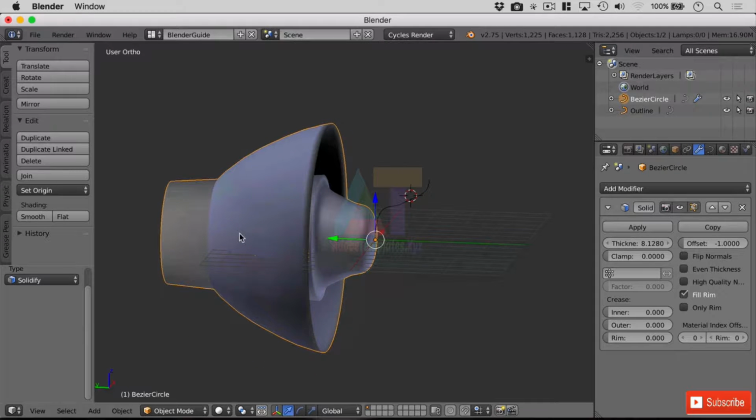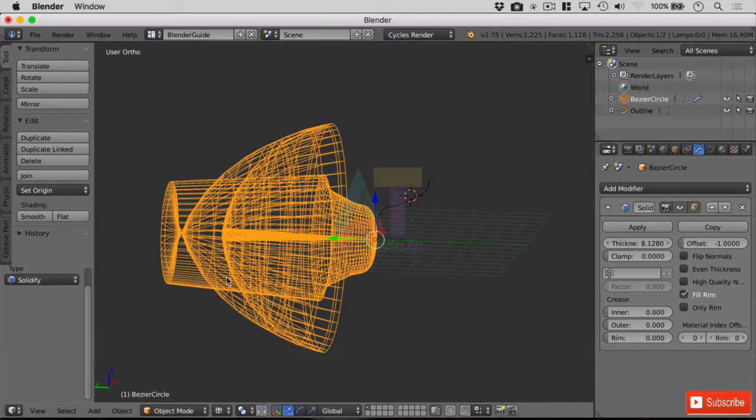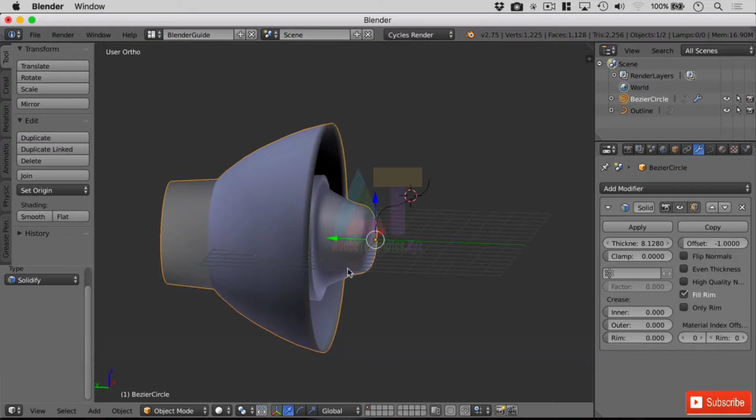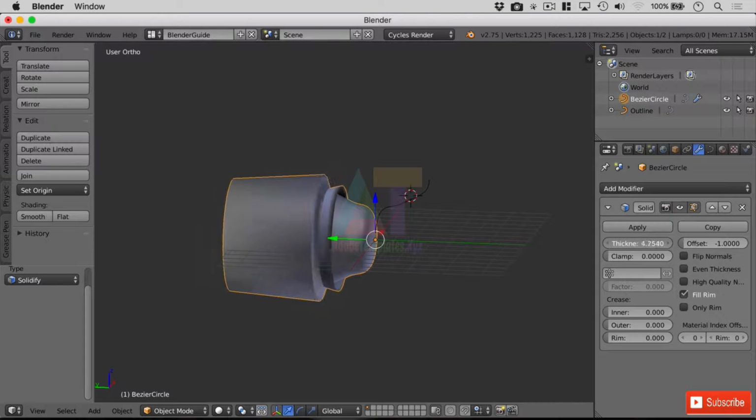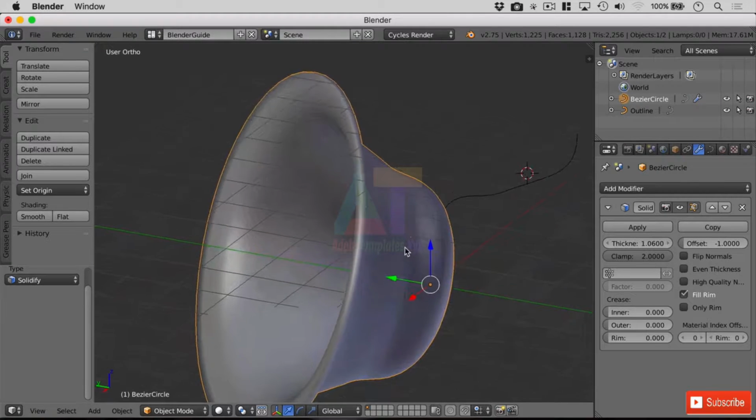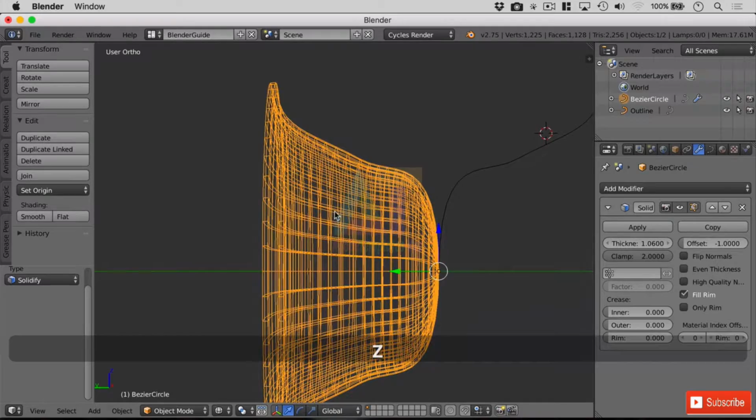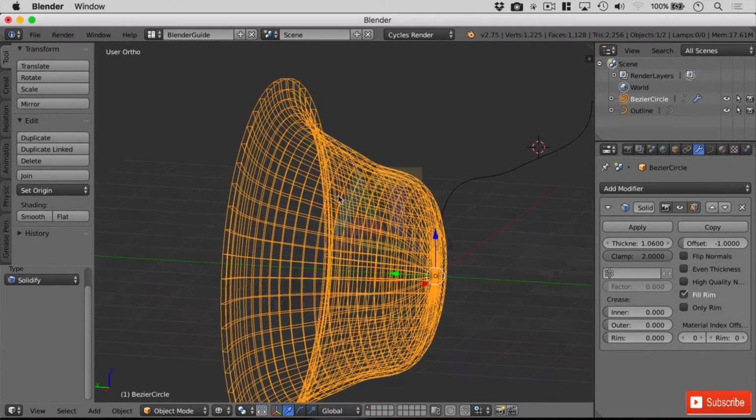But there's obviously a lot of geometry inside. It's a very messy model doing it that way. It would be much better just defining this with curves. So let's push that back. So sensible, and increase the clamp. And depending on how high you set that clamp, it's got a value between 0 and 2. Depends on the amount of clamping that will actually happen. So again, in wireframe mode, it gives us a good indication of wall thickness throughout.